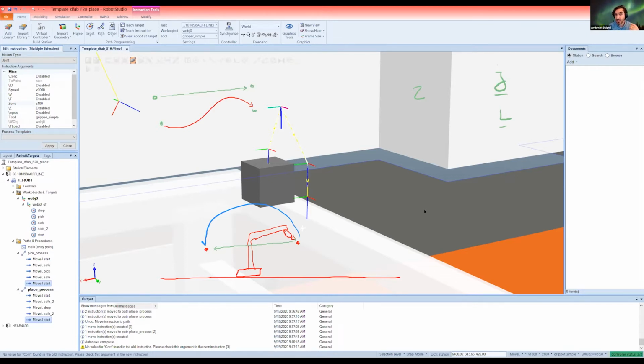Move L is really helpful when you want to make sure you have 100% control over what's happening. Move J is good when you don't want to be concerned with all these extra actions. The robot is going to take care of most of it. When we get into serious simulation, we will actually follow the tracing of the robot, and you will see how it is working.